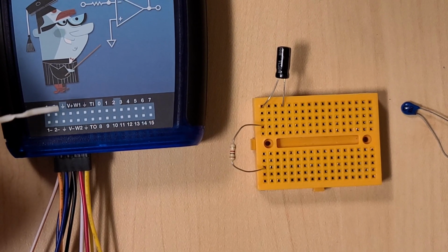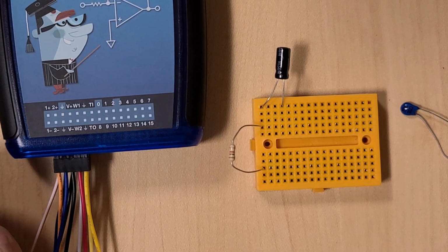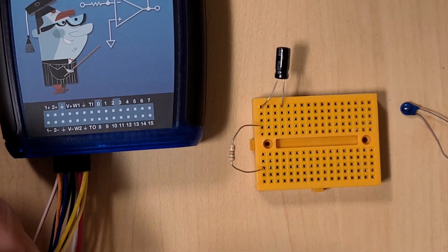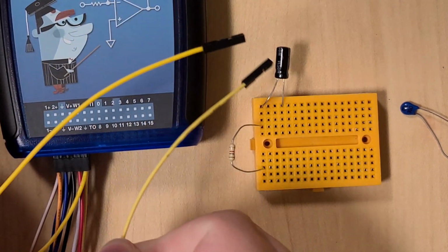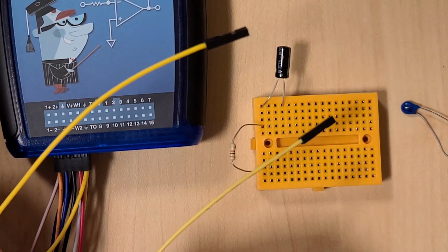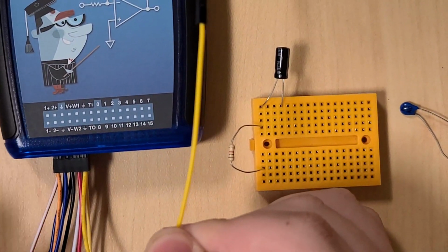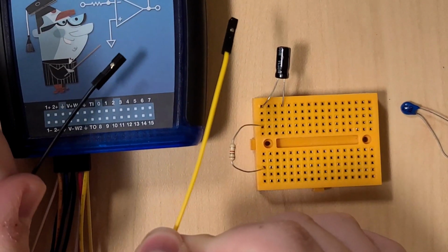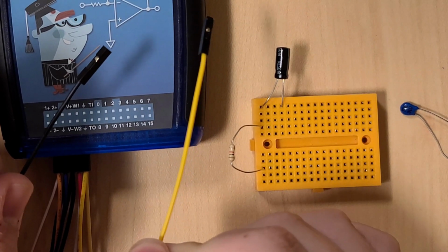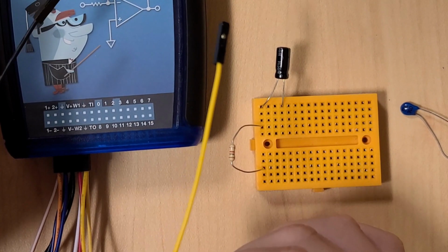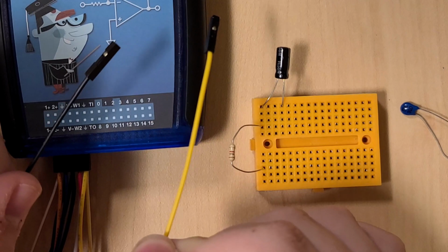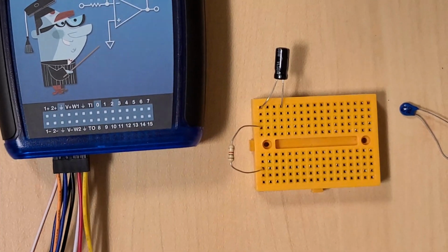Why that's important is, again, a lot of people are going to think that when this thing generates a signal, oh, this is my voltage source, these 2 wires. No, the WaveGen creates a voltage waveform in reference to the reference ground. So what we are going to make today, we are going to be dealing with just W1, and the negative supply of the voltage source is going to be the reference ground. So we'll talk about that a little bit more.